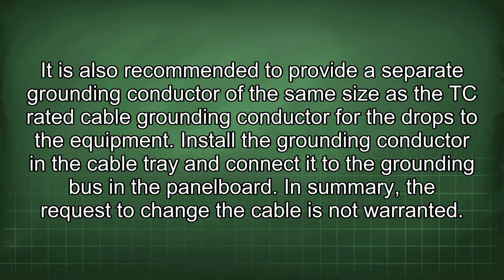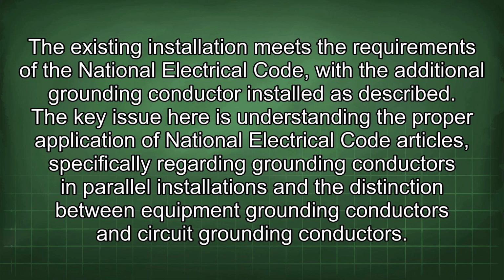In summary, the request to change the cable is not warranted. The existing installation meets the requirements of the National Electrical Code, with the additional grounding conductor installed as described. The key issue here is understanding the proper application of National Electrical Code articles, specifically regarding grounding conductors and parallel installations, and the distinction between equipment grounding conductors and circuit grounding conductors.